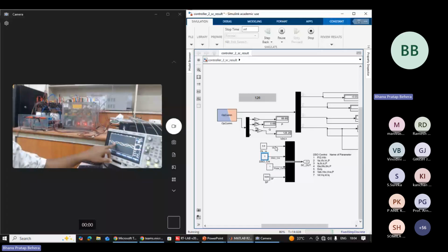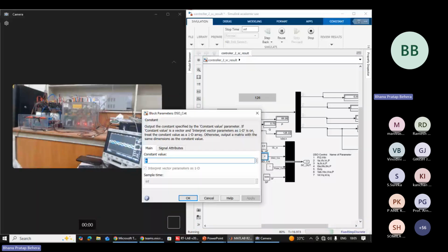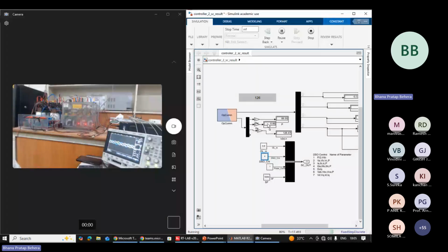And if you select the 4, you can see this is the current before filter, the actual current before the filter from the plant. And similarly, if you press, you can see the PQ. Here you can see the PQ, because this is a resistive load. Here Q is 0, P only having some value of 88 watt something.